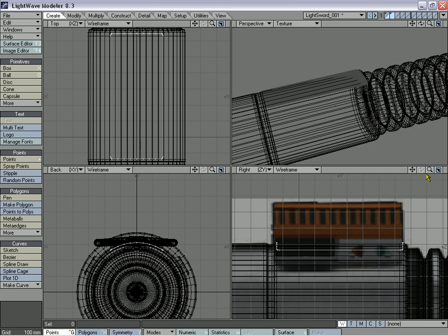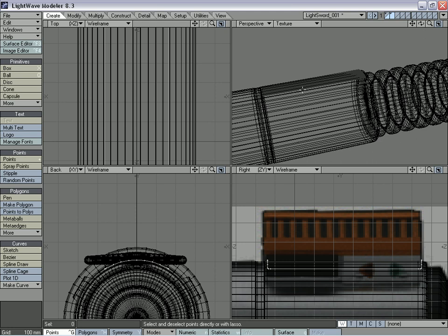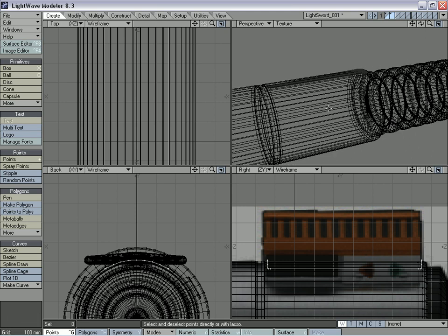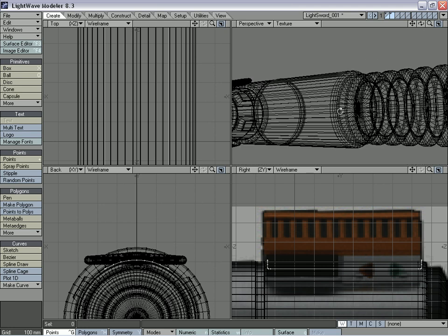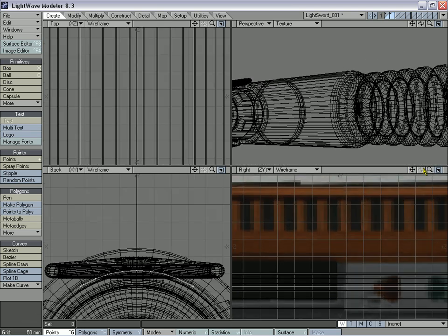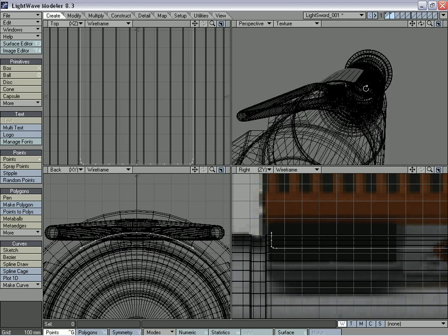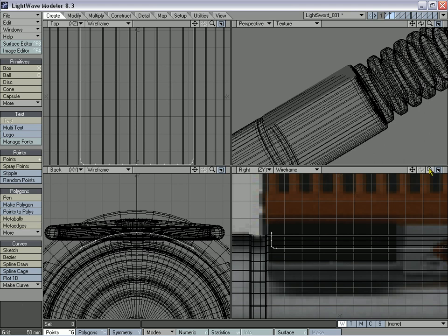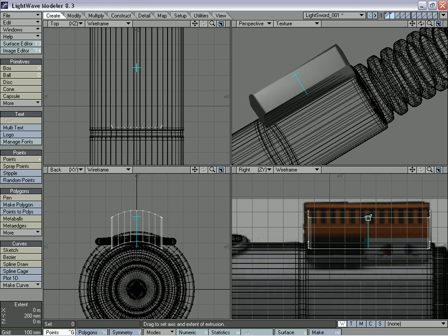And now we're going to use the extrude tool, and we could use smooth shift, but we want to keep this bottom polygon because we're going to be using it to kind of bevel downward into the other object. And we want to make sure we have enough space in here between the two objects so that we can have a nice curve in there. It looks like there is. Okay, so now we're going to use the extrude tool. And in order to do that, it's Shift E, and then you just pull out the section.